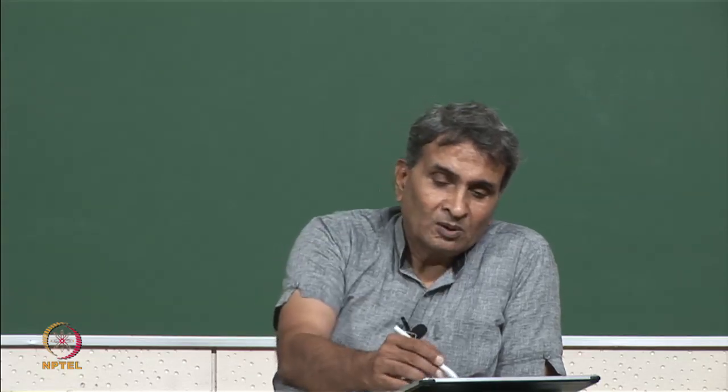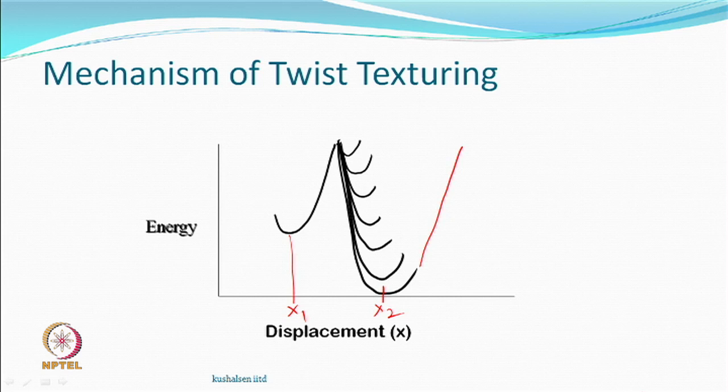If all of them go back to position x 2, then what do you get? Again a multi-filament twisted yarn, which is again not a textured yarn. So, how do we get the stretch and how do we get the bulk? We had only 3 steps: twist, set and detwist. We have done the detwisting. So, how do you get the texture? How do you get the bulk? How do you get the stretch? Any guess?